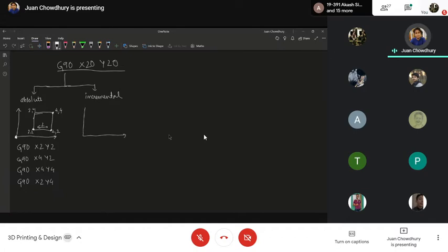But in incremental format, wherever the extruder was last set, that goes to the 0 position. Say it was at 0, 0 initially. I took it to 2, 2. The next point will turn out to be 2, 0. Then the next point will turn out to be 0, 2. This point will turn out to be minus 2, 0.